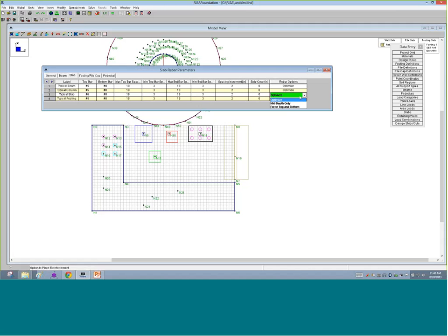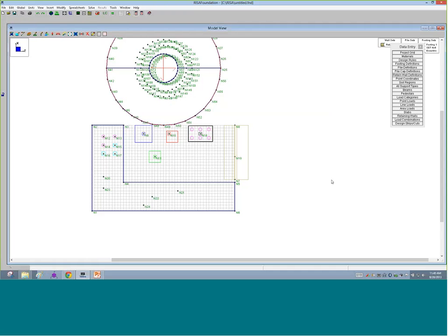Can you tell the program to do just bottom bars? Well, you can if it's needed. The way you tell the program to do just bottom bars is to say optimize. If it does require top bars, then you will get top bars as well. But if you only need bottom bars, and we'll see that in a common case coming up in another model, you can say optimize, and you should only see those bottom bars. Mid-depth only, we'll set that only at mid-depth, and then we can also always force top and bottom, but we'll just leave this as optimize.